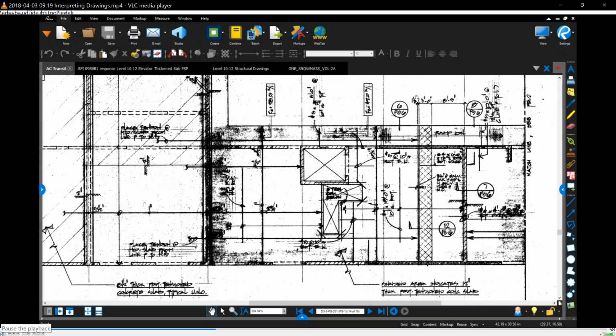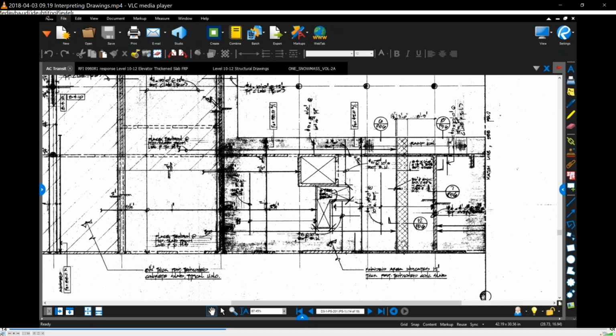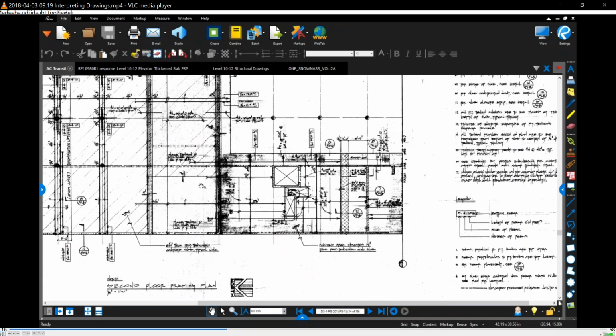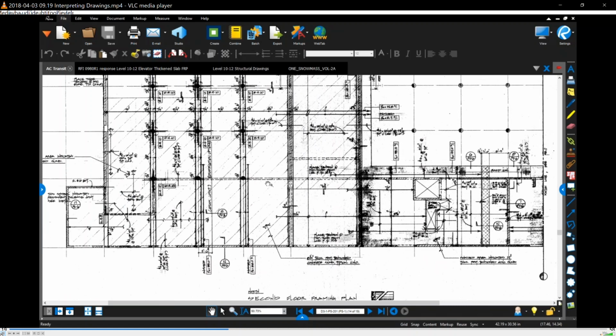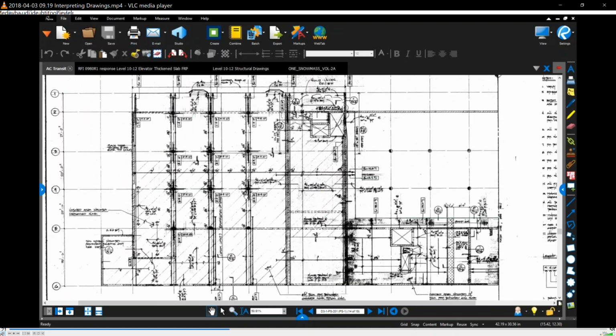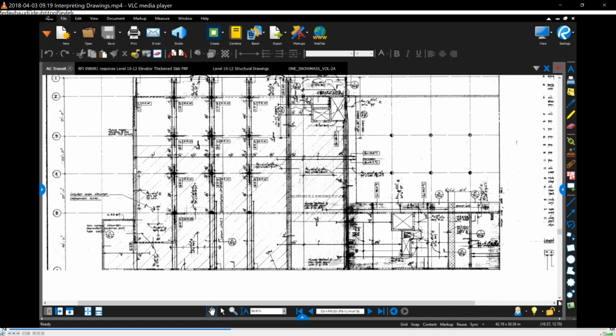If we were to go to this sheet, it would basically show they leave this section of slab out when they pour this section, and it allows the contractor to stress the cables in this block out. It also allows this portion of slab to shrink independently of this portion, which is better construction practice, and you get less cracking because of that. I don't see a construction joint on this slab, so it's small enough that the contractor can pour this entire piece in one pour.